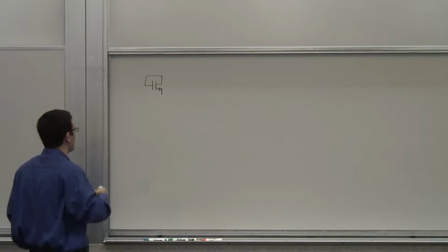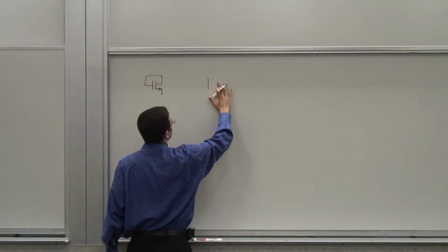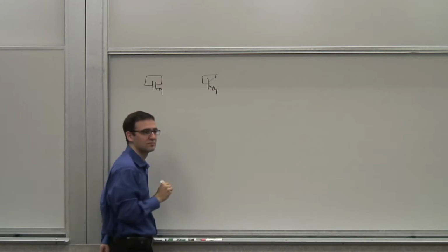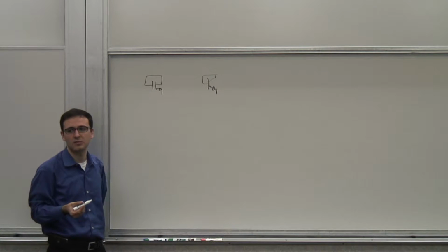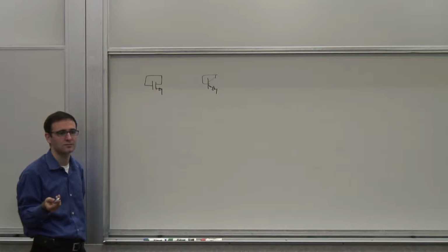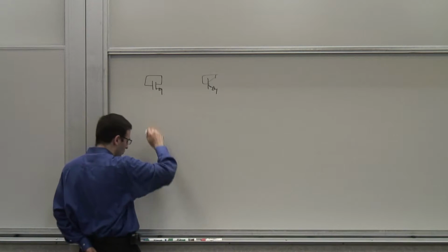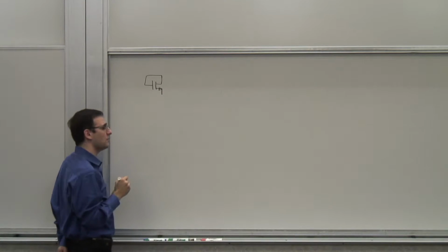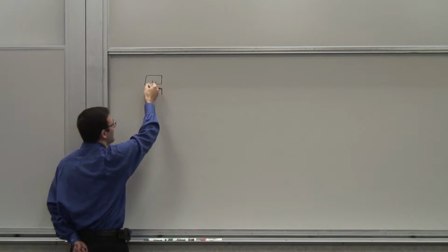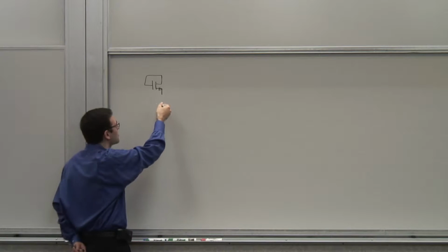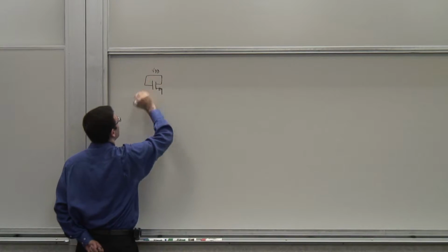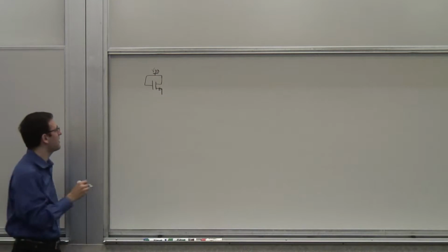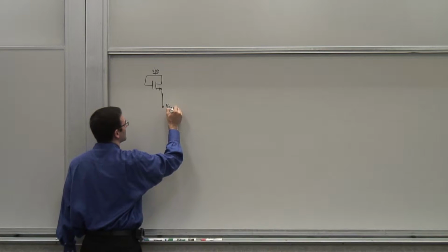And the reason is that if you do this in a bipolar transistor, you will form a diode, right? This is a PN junction diode. But basically it's the emitter-base junction. So if you try to do something similar to that here, you can have a structure like this. Now, of course, the drain side has to be at a higher voltage than the source, right? So let's say I connect this to the highest potential in the circuit, VDD. This terminal is VDD. Now this has one terminal, let's call this V out.